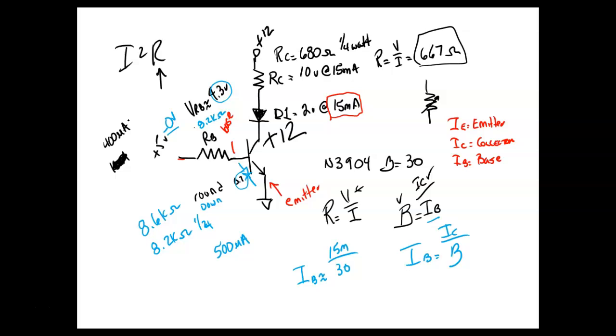The problem we have is when we saturate a transistor. Normally what we're supposed to do is keep this guy here reverse biased. When we saturate the transistor, then this guy here is going to drop a little less than 1 volt. So I might have 0.1 volt right here, or 100 millivolts right there. And then I've got 0.7 of a volt right there. So what actually happens when you saturate a transistor, it actually forward biases, or tries to forward bias, it'll never get 0.7. It'll try to forward bias the collector-base junction.